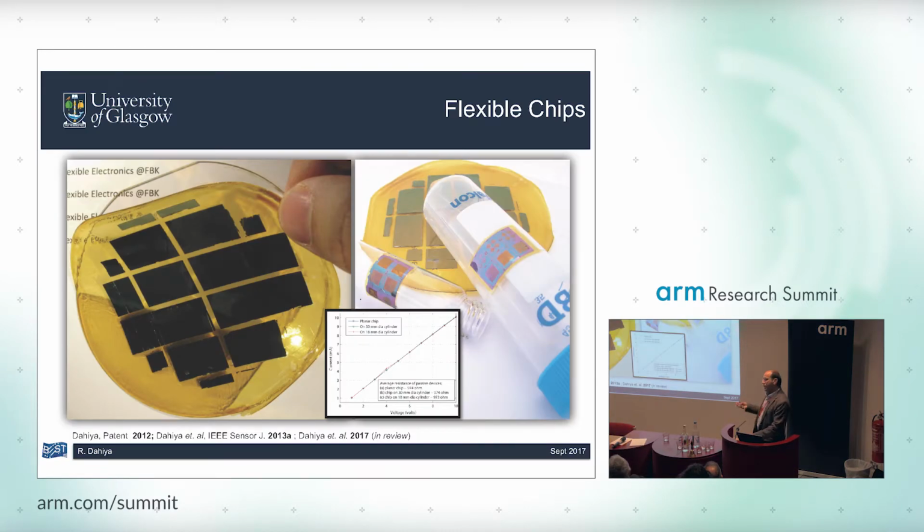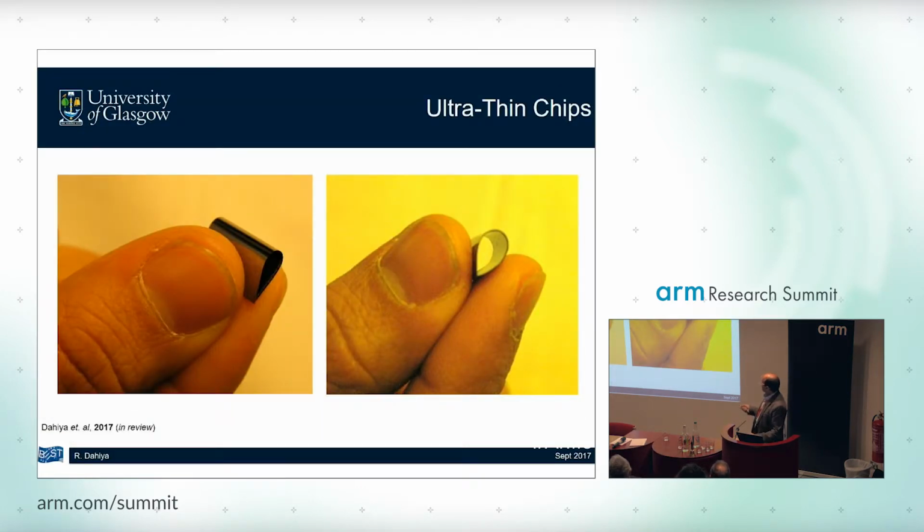Now coming to inorganic, we started, as I mentioned, ultra thin chip work. We came up with this nice process, which is wafer scale chemical etching, and getting ultra thin chip. This is a new technology that we developed, and the silicon in this case is 1.5 micrometer thick. The conventional grinding technique leads to about 50 to 70 micrometer, but in this case we were able to get the wafer scale process, and that's the kind of bendability you get with silicon.